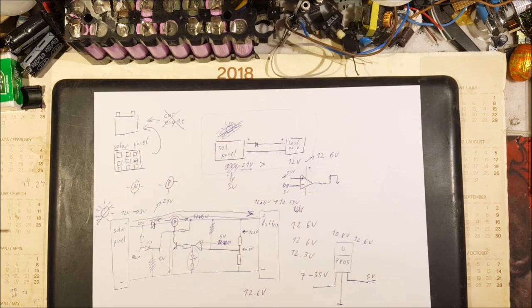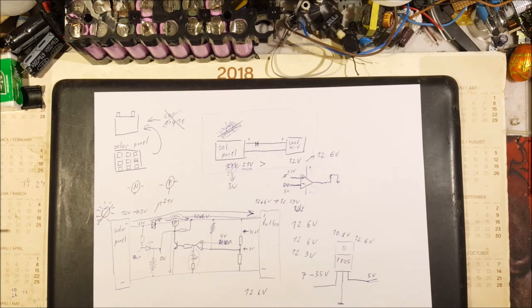And that is a problem because that means that our LED is going to illuminate when this MOSFET opens, and it will open when the charging is done, and we want the LED to turn off when the charging is done.